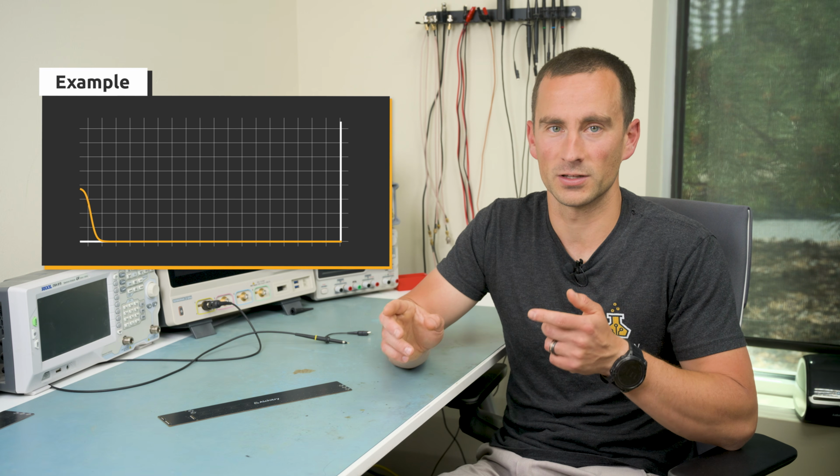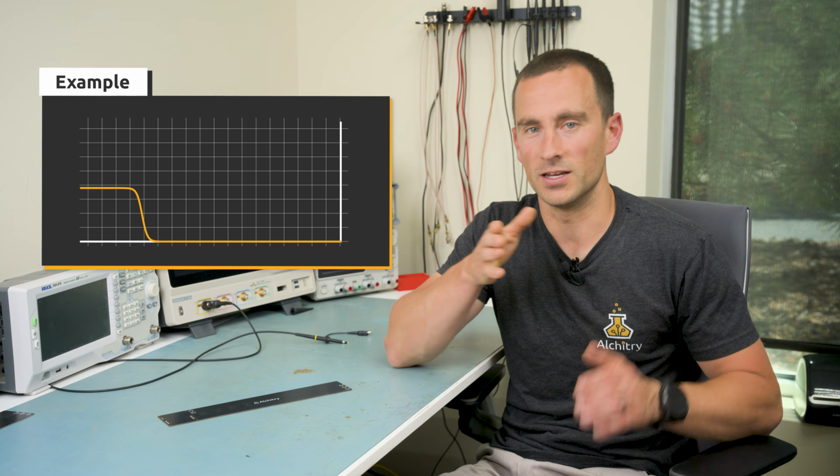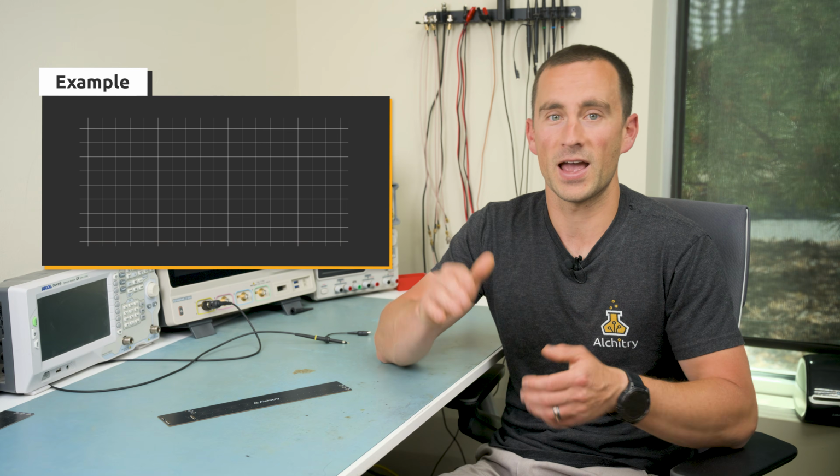How is that even possible? Well, if we think about a wave moving down the transmission line, when it comes to the end, it has nowhere to go except backwards, so it completely reflects. Right at the point where that happens, the incoming wave and the reflecting wave overlap, adding up. We can actually see this happen on our demo board.